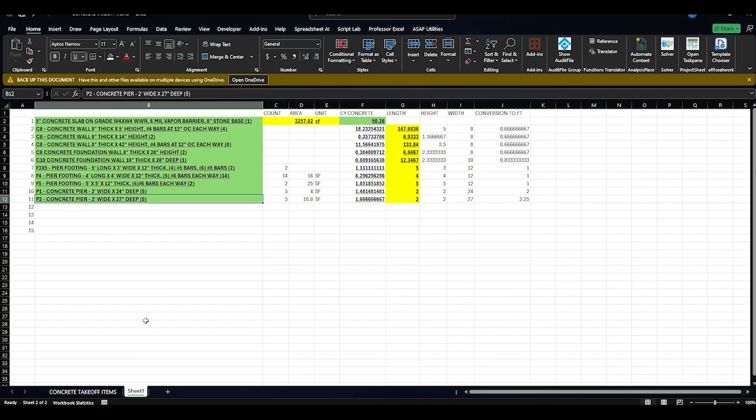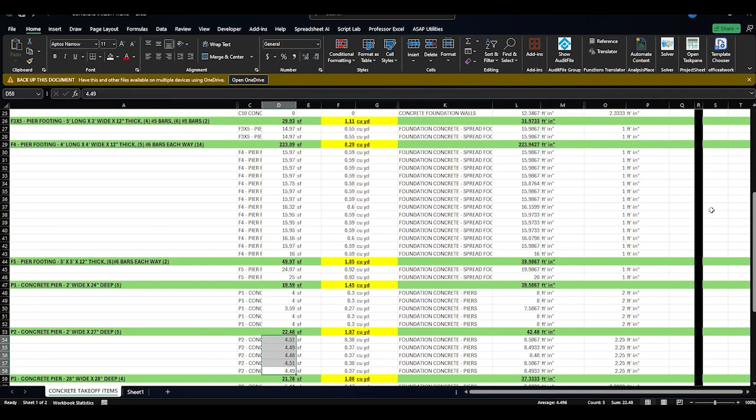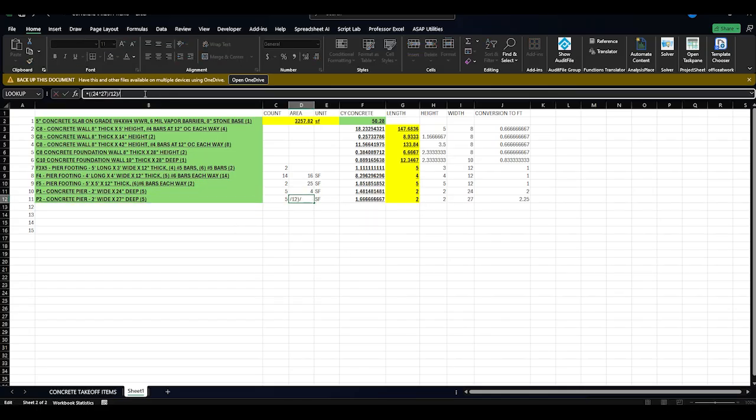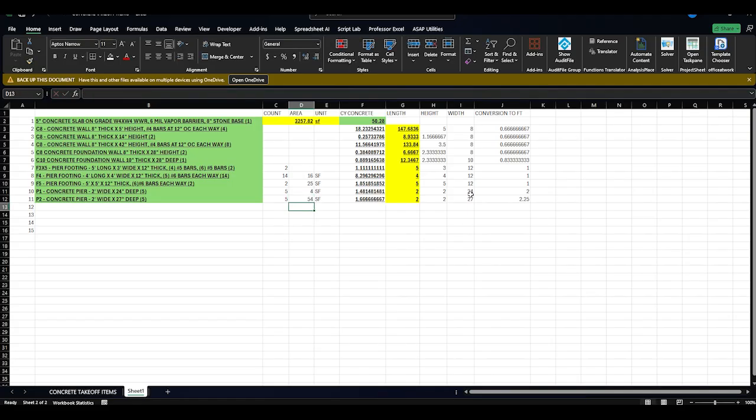On this particular item, I was having difficulty with the quantities not matching through the conversion process. I knew there was an error, and it took me a minute to figure it out. If you recall from the work in Bluebeam, I mentioned that taking off the wall footings with the area tool made it more complicated because I didn't have the quantity for lineal feet. I eventually worked this out and got the data to match up and continued down the list.